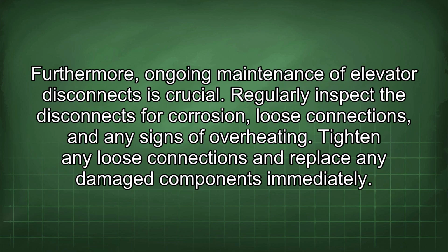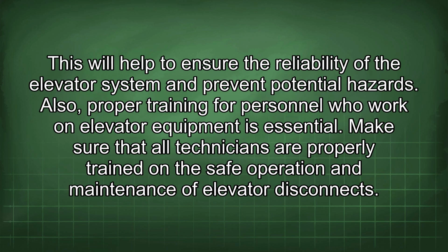Furthermore, ongoing maintenance of elevator disconnects is crucial. Regularly inspect the disconnects for corrosion, loose connections, and any signs of overheating. Tighten any loose connections and replace any damaged components immediately. This will help to ensure the reliability of the elevator system and prevent potential hazards.